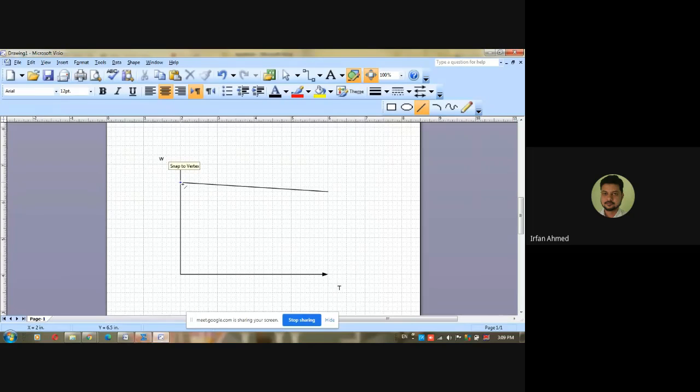If we insert external resistance in series with the motor armature, the no load speed of the motor does not change, it remains the same. However, the slope of the characteristic increases, and this will be the nature of the characteristic for some resistance R1. If we further increase the resistance, this will be the characteristic for some resistance R2, which is greater than R1. If you go on increasing the resistance, the slope goes on increasing. Okay, is this clear, everyone?